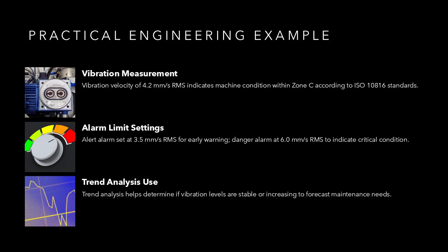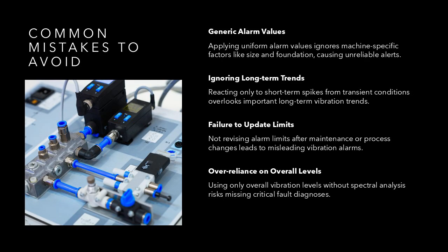Trend analysis would be used to assess whether vibration is stable or increasing. This example demonstrates how standards, measurements, and engineering judgment combine to form an effective alarm strategy. This slide highlights common engineering mistakes in vibration alarm implementation.